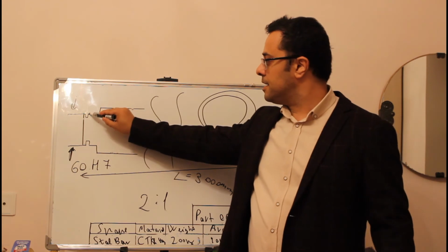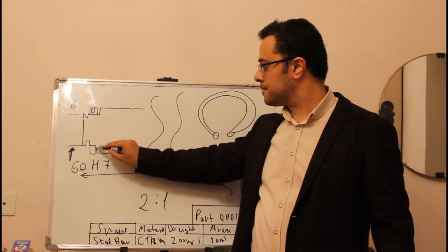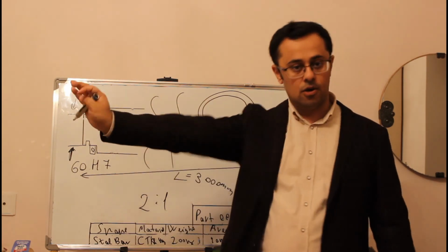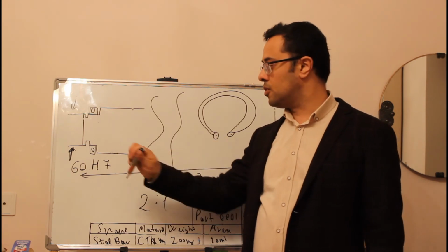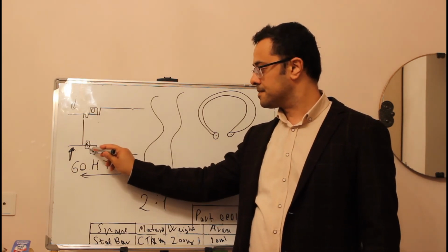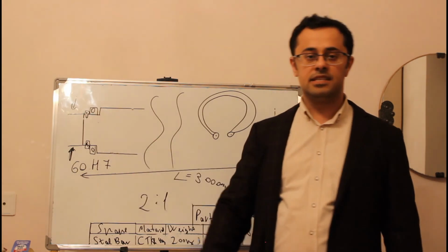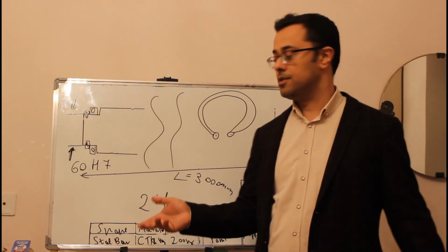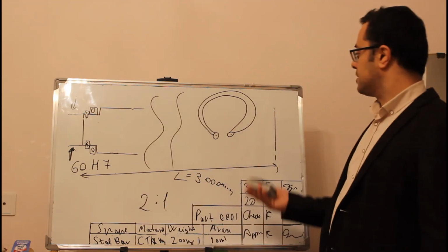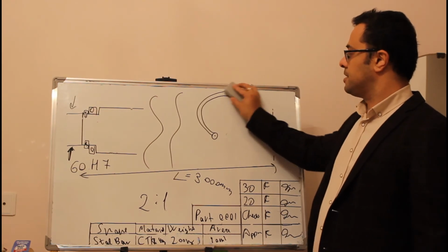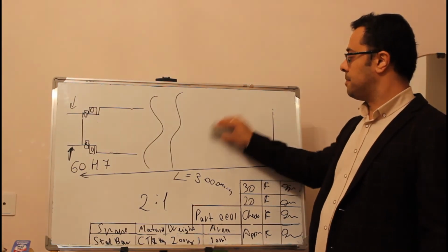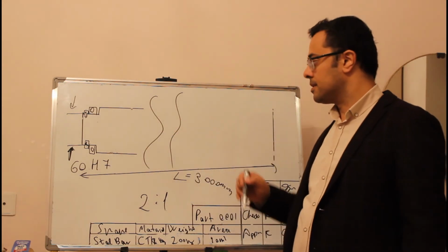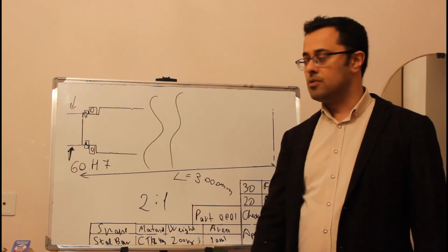As you see, this is the bearing, and it cannot go in this direction because there is a shaft wall, but it can go up. So for it not to go up, you put a ring here, and this ring is installable and uninstallable. You can put it and take it out whenever you want. That's the ring you need. Rings vary by diameter and by application. It can be internal or external. Here it's an external ring.